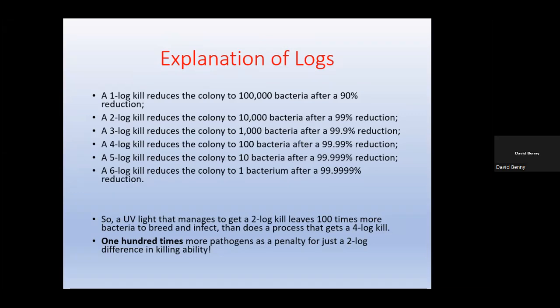If you look at the environmental management rules in Trinidad and Tobago, our schedule for the water pollution rules with respect to E. coli bacteria is 400 colonies, except for environmentally sensitive areas where it is between 200 and 100 colonies. So indirectly we're telling you that your UV system must be designed for 4 log kill. So you're reducing 99.9% of the bacteria in the sample.